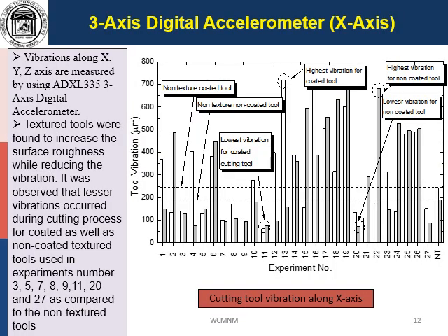As I mentioned before, a triaxial accelerometer ADXL335 was mounted near the contact on the tool holder shaft which held the cutting tool insert. It was noted that most of the textures with 80 micrometer distance from the edge and having 100 micrometer pitch generated low magnitude vibration compared to non-textured surfaces. This happened due to the improved bonding of lubricant on the textured surfaces.